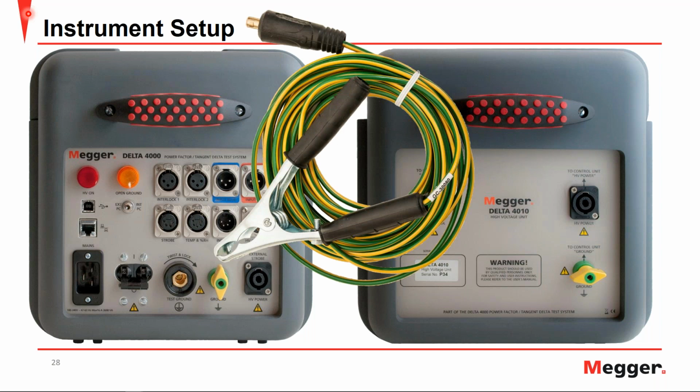You have the ground cable we're talking about, and this is the twist and lock termination that I was talking about, the connection to the Delta. And then you can see this is to the test ground, so you would connect this to the transformer. And one thing to note of this is, the Delta 4000 does monitor the ground. As we were talking about, it is a single point ground. And if the grounds are not a common ground and there is an open ground, this open ground LED will illuminate until you have a single point common ground, in which case it'll turn off.